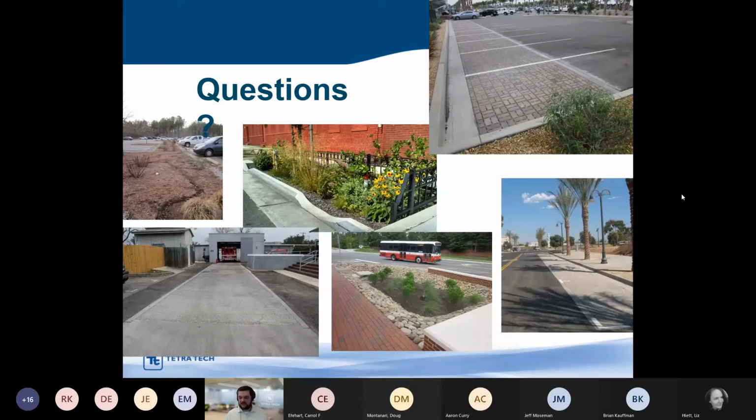Okay, have you heard much from maintenance crews about problems with water getting under the road when using permeable gutters or pavement? I have not, but that's because I always make sure my BMP, anything I put next to the road, has a liner. I know it can be an issue. I haven't really heard of anyone that directly blames issues with the roads on that, but I've had the same conversations convincing transportation engineers that putting a bioretention area next to a road isn't going to cause the road to be swallowed up in a giant seep hole.